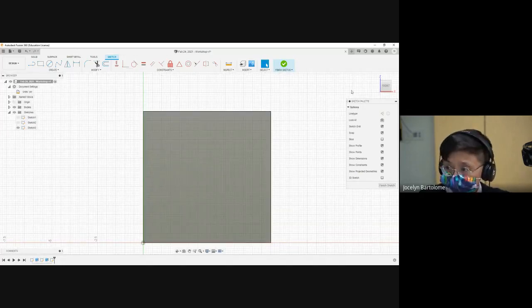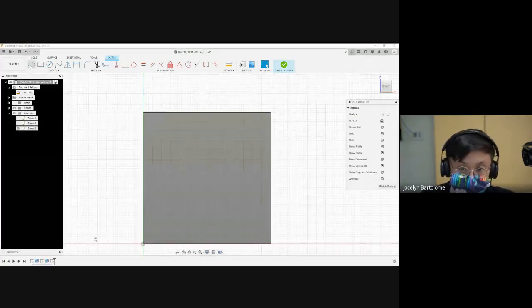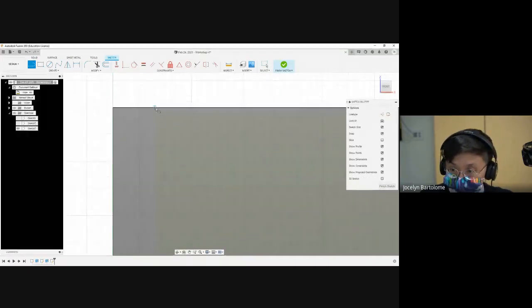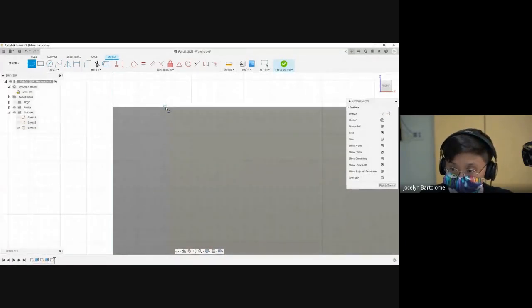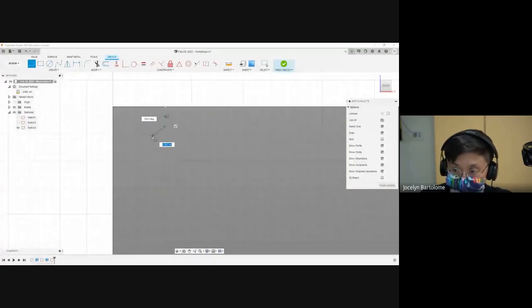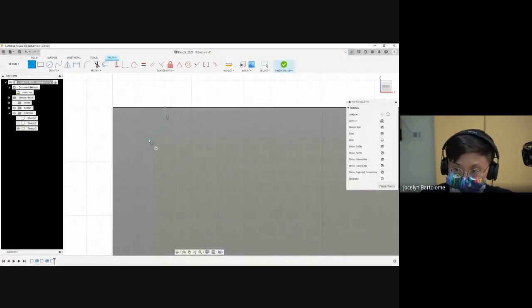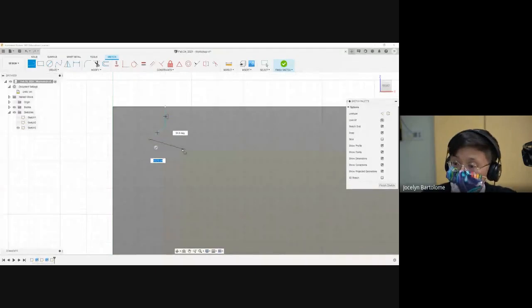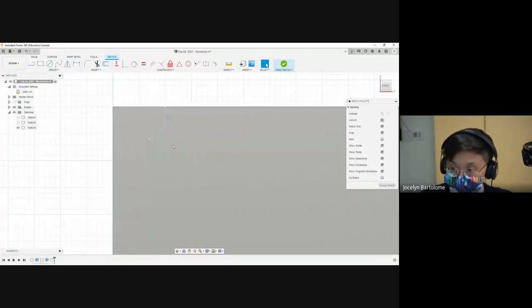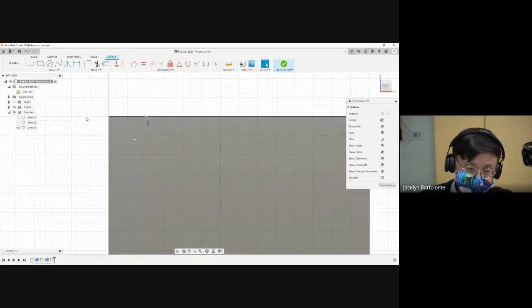And again, we are back inside the sketch menu. And this time we're just going to create a line. So there's a line right here. Click on that. And what we are going to do is start on the top edge of the cube, click that, draw a vertical line down, and then draw a line out to the left at some angle. Right now, the dimensions don't really matter. I'll show you how to dimension that later. But after you've drawn those two lines, you can just click Escape, and it will toggle that function off.